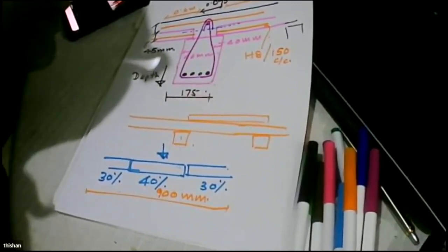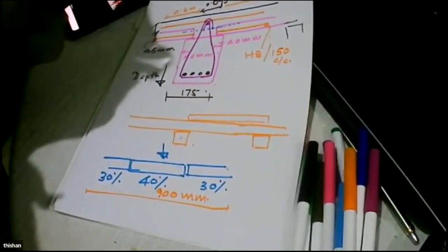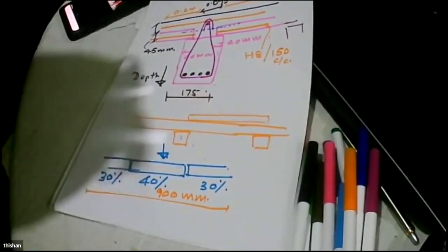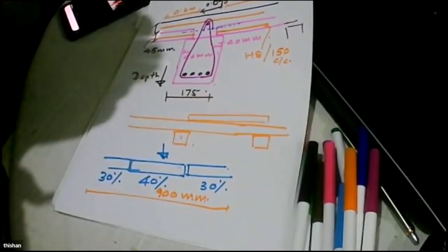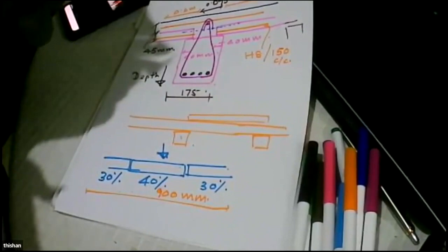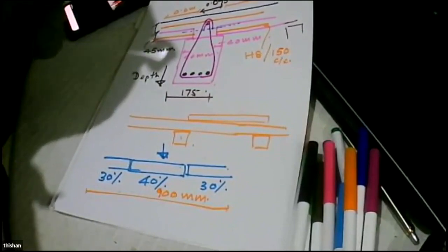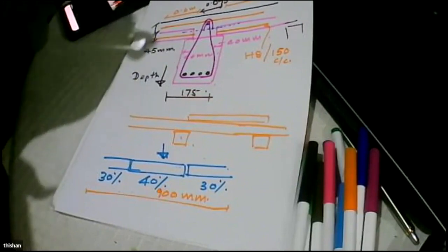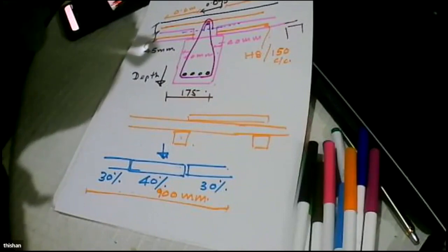Is that clear? Okay, sir. Yes, sir. And then can we use precast slab and beam for washrooms and roof slab? Precast slab is very good because on top of that we have a screed, high quality screed, not just the normal concrete. And because of the design, you can easily have a washroom up to a width of 2 meters with precast slabs.